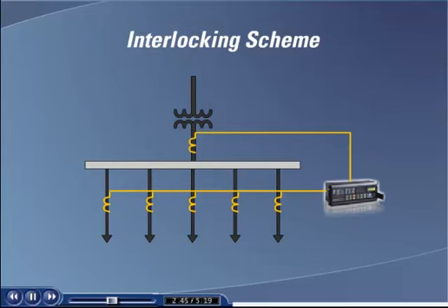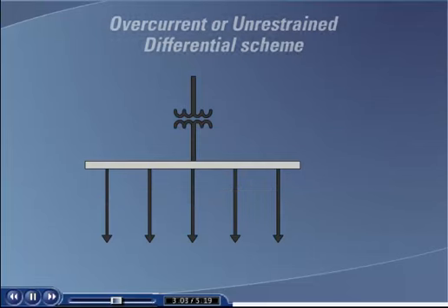Modern microprocessor relays, which have a fast peer-to-peer communication service, such as the UCA GOOSE messaging mechanism, can be used to send the blocking signal, eliminating the relay-to-relay hardwiring required for the block signal. The scheme, although easy to apply and economical, is limited to specific simple busbar configurations.